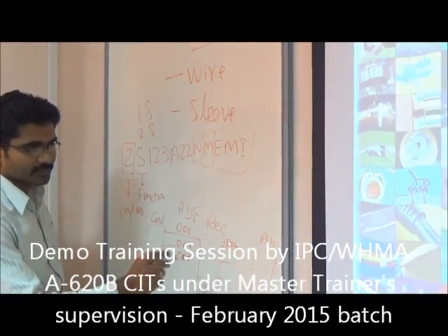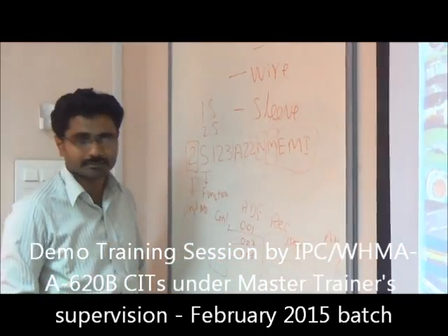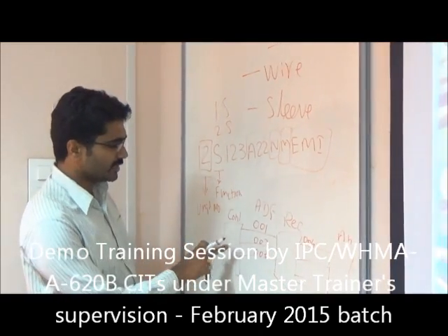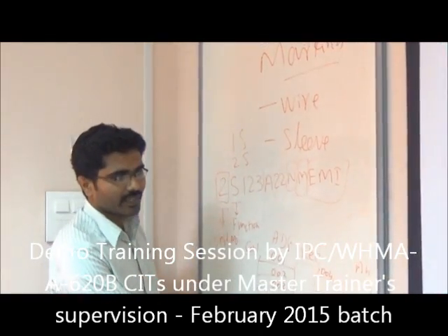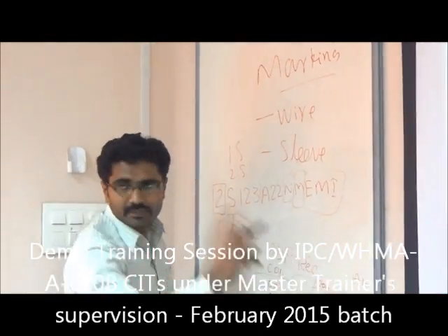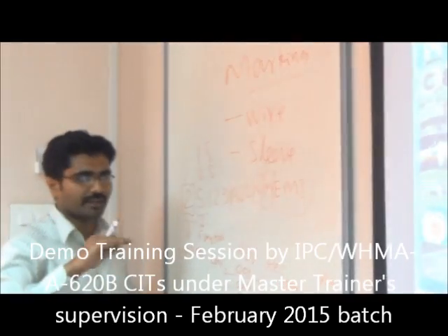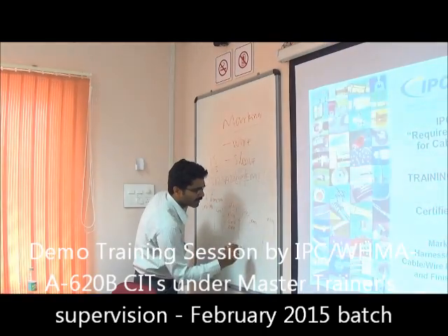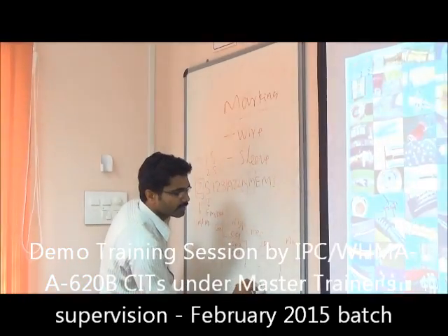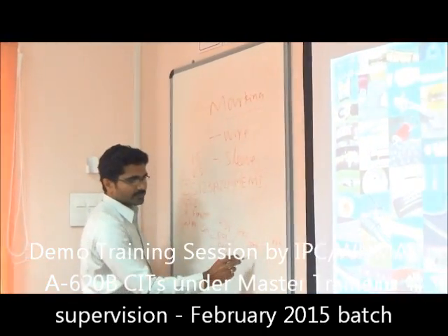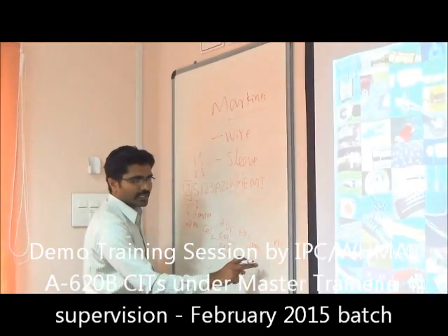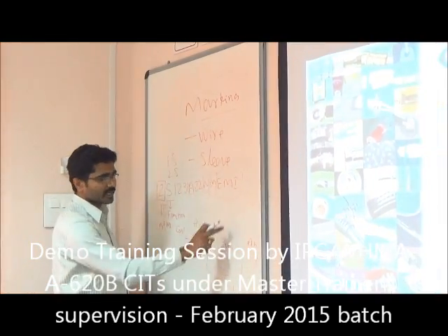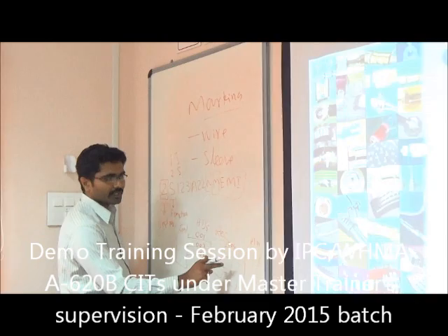If some wire bundle goes through a bulkhead connector, for example, this will be in the cockpit, this will be in the avionics bay, this antenna will be on the frame of the aircraft. In between, there will be a bulkhead connector. There should not be any leakage of air. This is a compressed area, so there should not be any leakage.